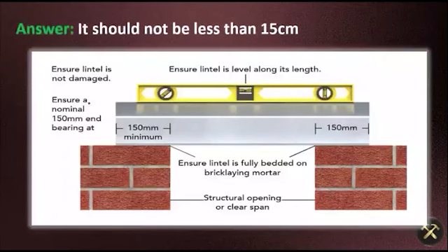The correct answer is it should not be less than 15 centimeters. So when you are making the lintel, it should rest at least 15 centimeters on the wall on both sides. If you want to go more than that, you can keep more, and that's good, but it will cause more expense and material. But you cannot go less than 150 mm, that is 15 centimeters.